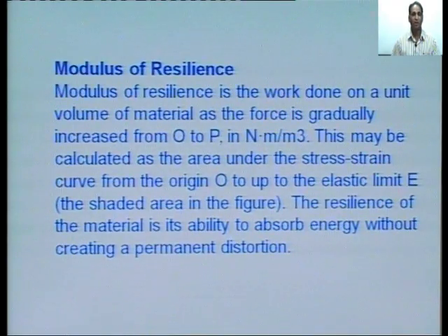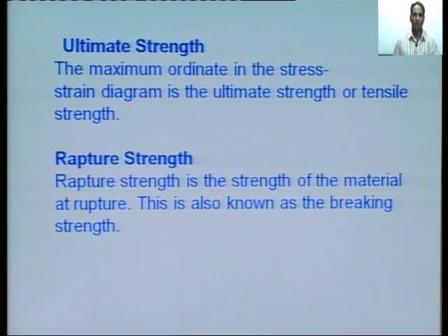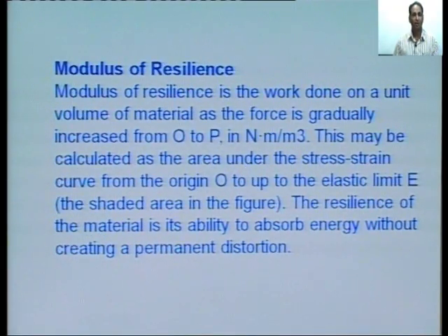So, this is the shaded area in the elastic region from O to P. The resilience of the material is the ability to absorb energy without creating a permanent distortion. So, without distortion, the maximum amount of energy the specimen absorbs is called the resilience of the material.